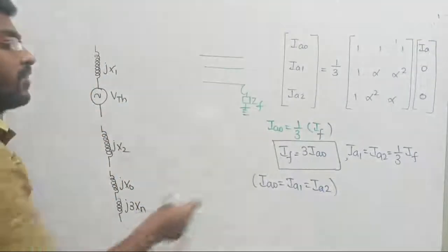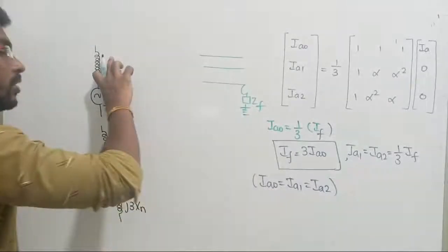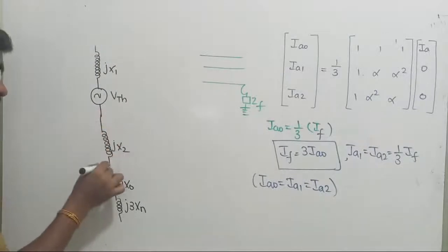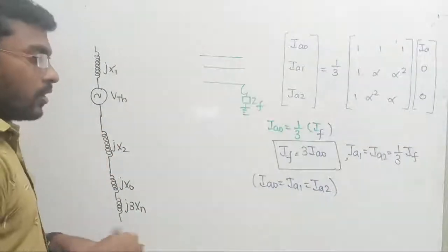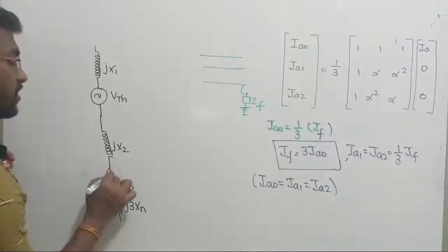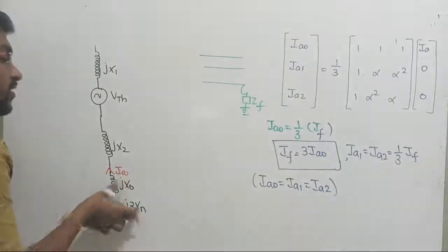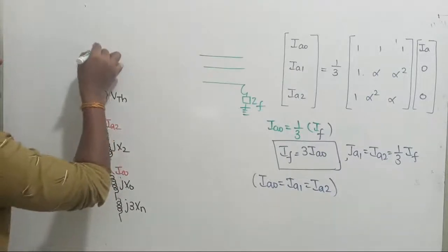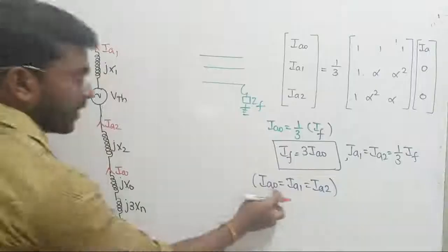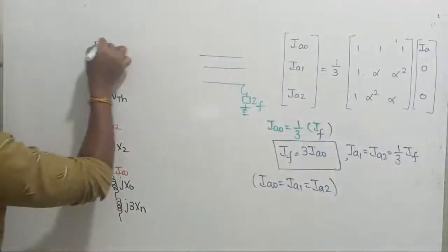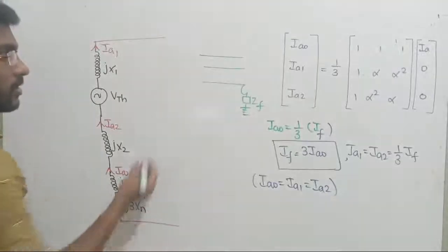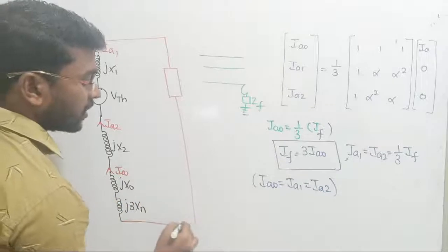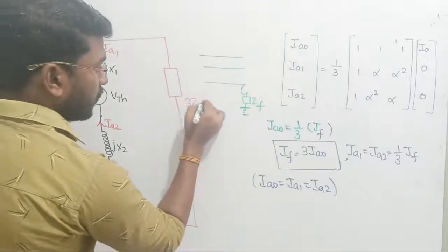Yes, that is over. But we understood one more thing: the positive sequence circuit, negative sequence circuit, and zero sequence circuit are all going to be attached together. The conclusion is that the zero sequence current is Ia0 from the zero sequence equivalent circuit, the negative sequence current is Ia2 from the negative equivalent circuit, and the positive current is Ia1 from the positive equivalent circuit. But Ia0, Ia1, Ia2 are all equal, in the sense that they are going to be connected in series. If fault impedance is given in your question, you have to consider that effect also. But 3 times ZF. Why?